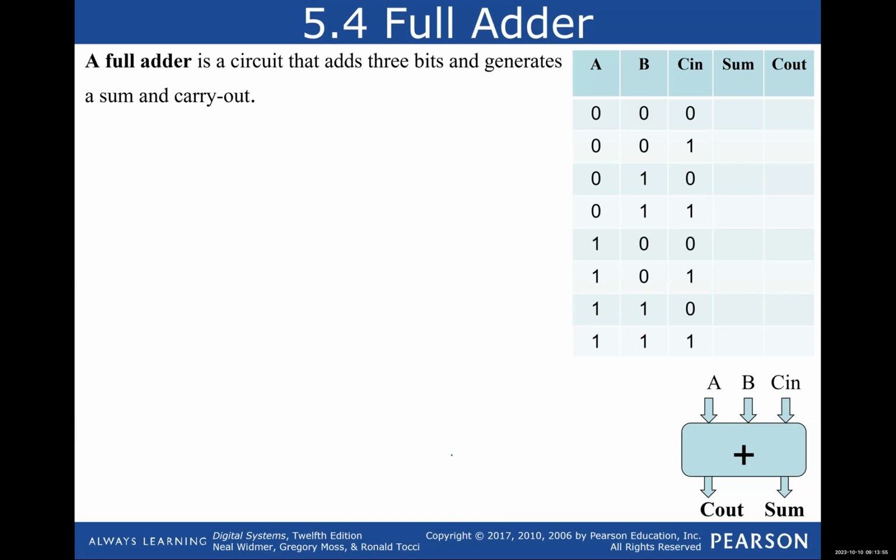I want you to write down the expression. I will call out a certain table to tell me what the minterms are. We want the sum of minterms? Yes, I want the sum of minterms for the sum and for the carry out. You're going to look where it's equal to 1 and add those together. Then we're going to minimize and simplify it together.